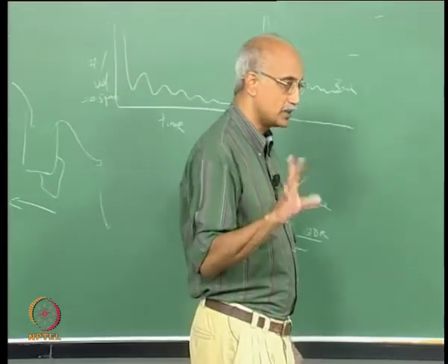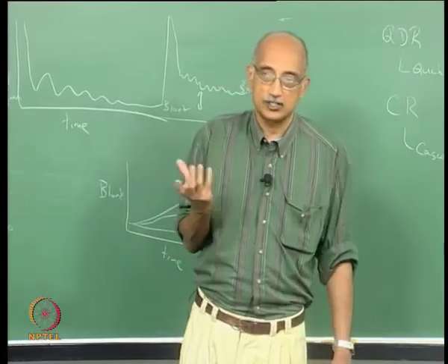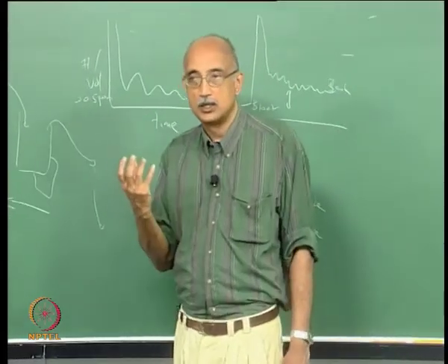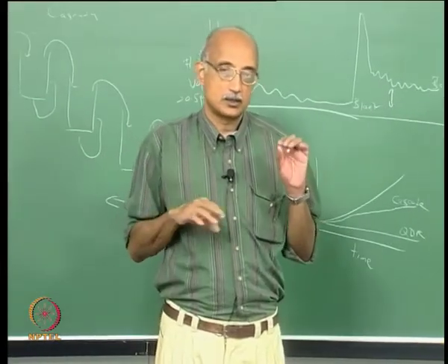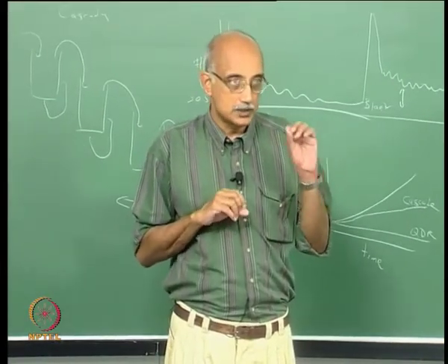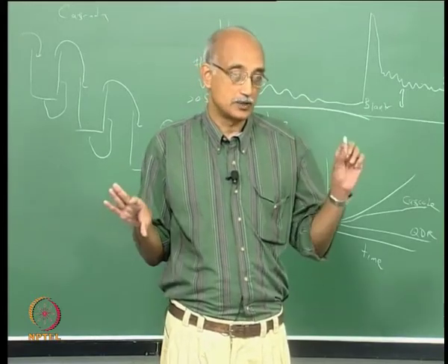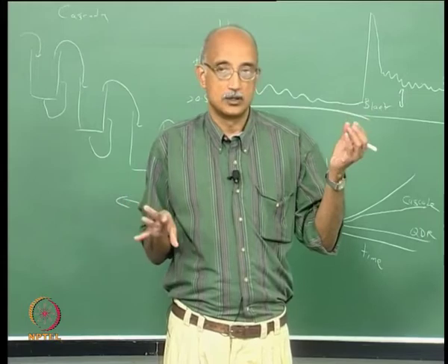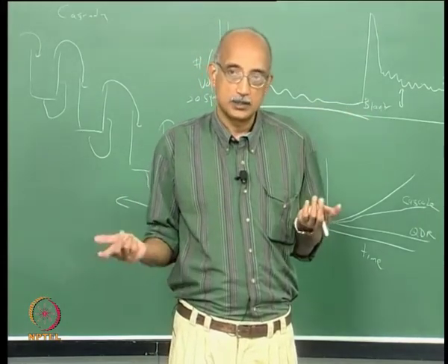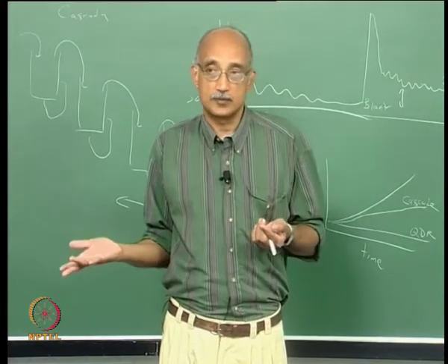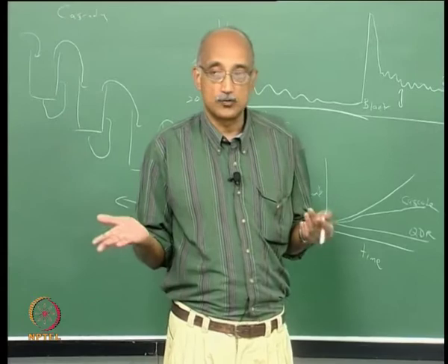And just like we discussed in the context of making nanoparticles, where again the challenge was to take a solid material and convert it into a vapor phase. The difference between a nanoparticle synthesis reactor and a thin film deposition reactor is that in the first case, particles are desirable. You are actually trying to make nanoparticles by using this process. In the latter case, where you are trying to make thin films, particles are a contaminant. You want to design the system so that particles do not form.